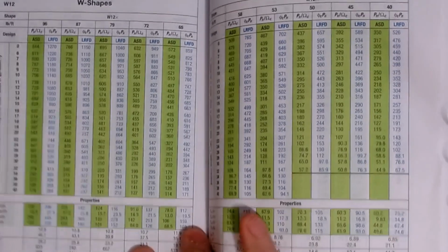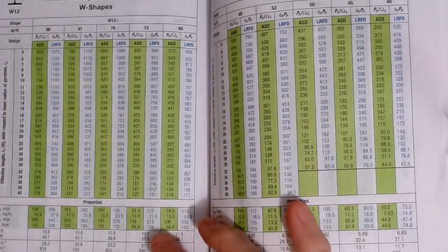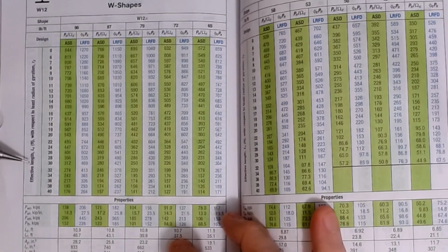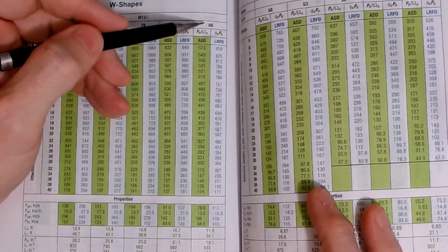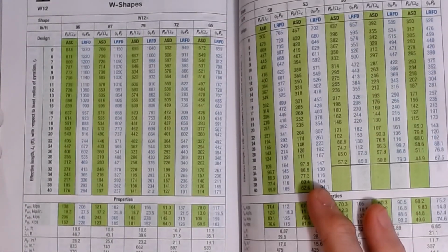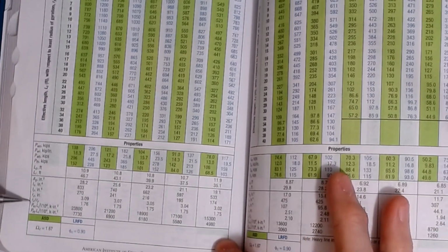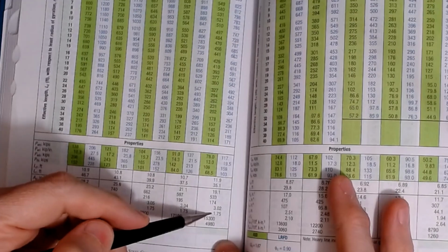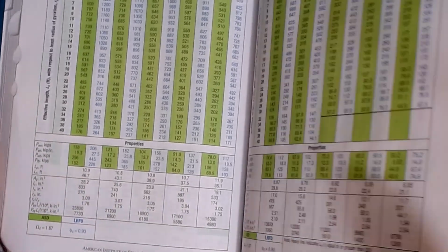If we come up, so again, we're paying attention to this note. This is what's causing me to have to do this calculation to check the strong axis direction. Okay, and so if I do that, if you come all the way down to the bottom, the RX-RY ratio is right here. It's that value right there. And so if I read across, it's 1.75 is the number that we need to do our equivalent.